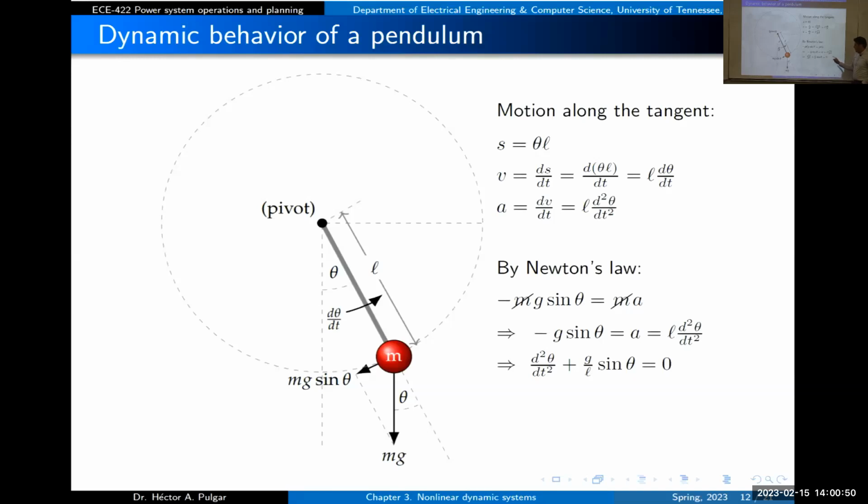So the first derivative of theta and the second derivative of theta is going to be sinusoidal. So how is the behavior? Oscillation without any damping, right? So if I start the ball here and I let it go, what we expect is that the ball will start moving forever between these 2 points, yeah, and will oscillate, right? Because we're not adding anything else. We can add some friction, and then this movement will start decaying in time because of the friction until we reach that point. That's what we expect. But at this point, we don't have any friction.